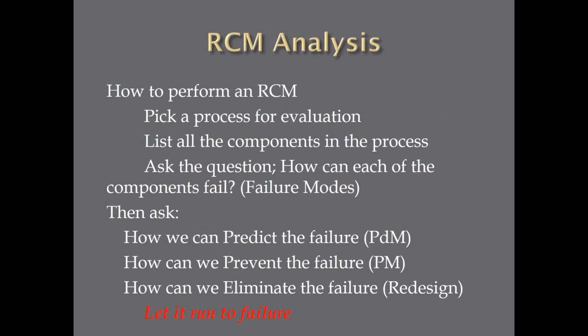So again, to perform an RCM analysis, and I'm actually going to do one tomorrow for a company, you pick a process in your evaluation or a piece of equipment. You list all the components in the process, and then for each of those components, you ask the question, how can or how has that component failed in the past? And then we're going to ask, how can we predict the failure with a predictive technology? We're going to ask the question, how can we prevent the failure with a preventive maintenance task, a PM?